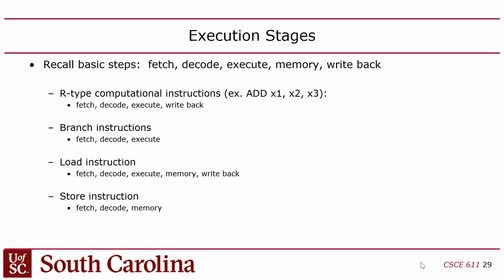If you have an instruction like a branch, it will be done in 3 cycles, but an instruction like a load takes 5 cycles, right? That way you can have a very fast clock. Whereas with a single cycle CPU, your clock speed is going to be slower because it has to be long enough to accommodate the most complex instruction, the instruction with the most data path going on, which is usually a load.